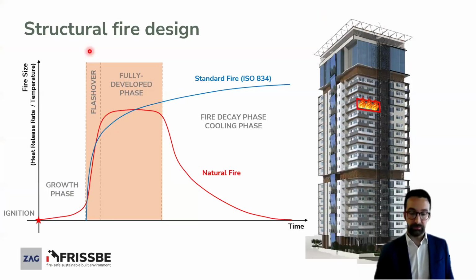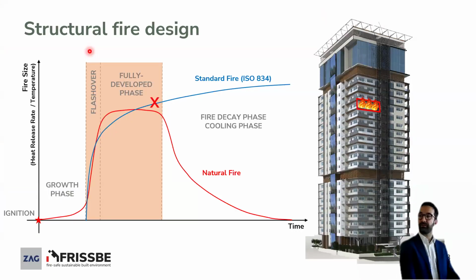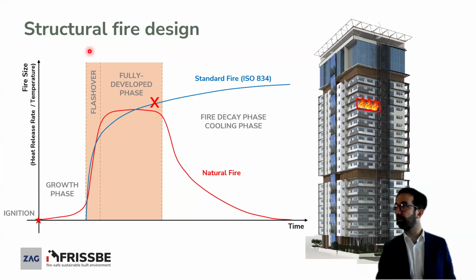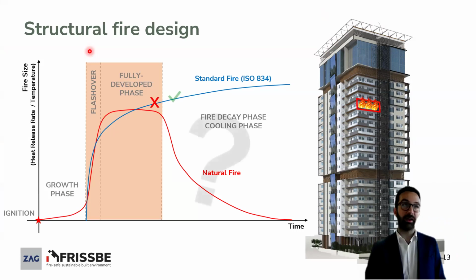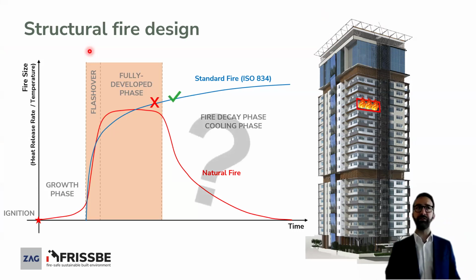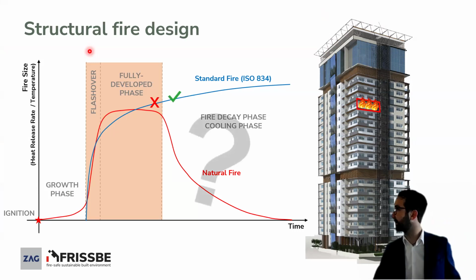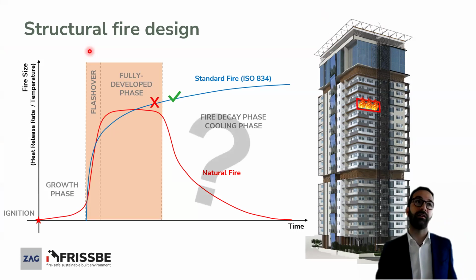So what we do, if the sample fails during the actual duration, that is the fire or the definition of the fire itself, then this is a problem. If actually the element survives and carries the load and does the job during the specific duration, we are happy with that.